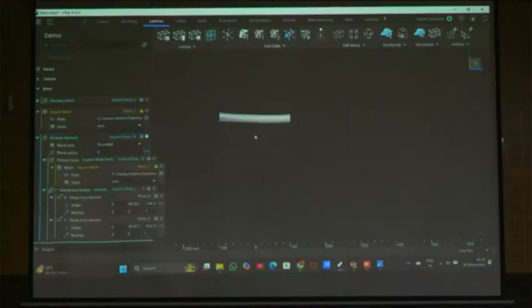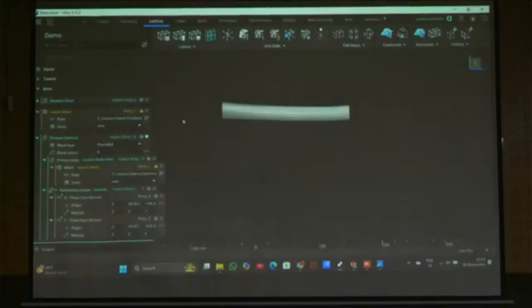So you might have a doubt: we can do the same operation in SolidWorks or other software also. But the problem is, with SolidWorks we cannot work with STL files, right? So nTop, or Magics, Mimics, these can support STL files. There we can separate the bodies. But I am using nTop and separating the two bodies, okay? So I will apply the lattice. First what I will do is